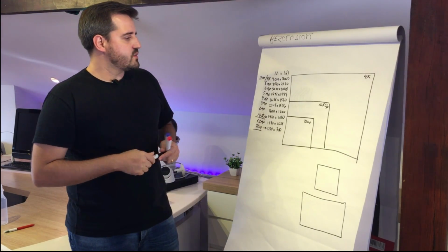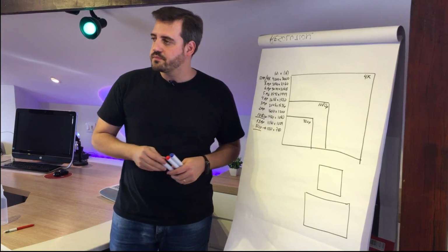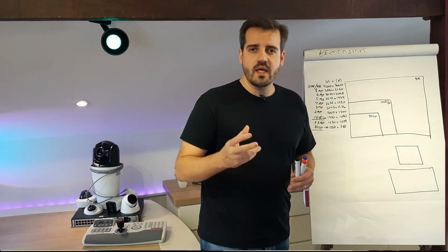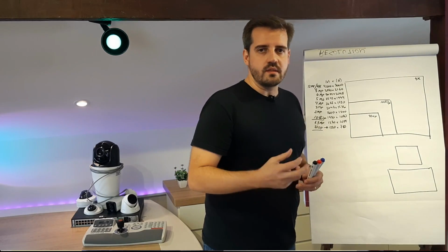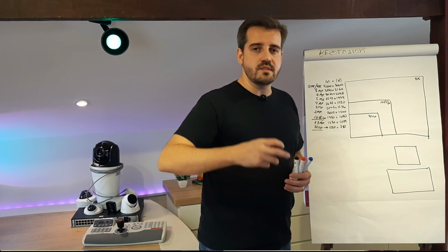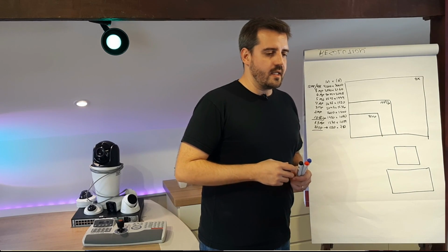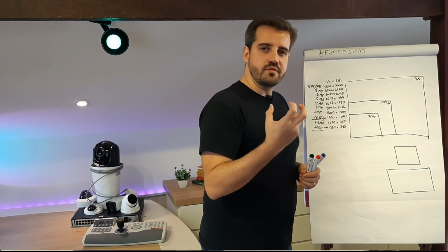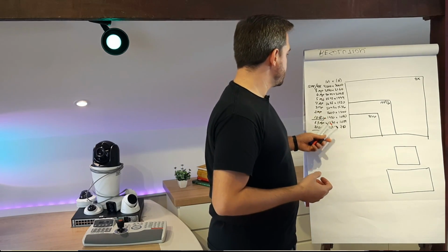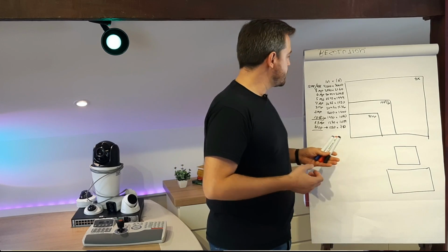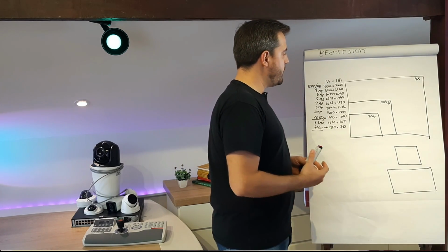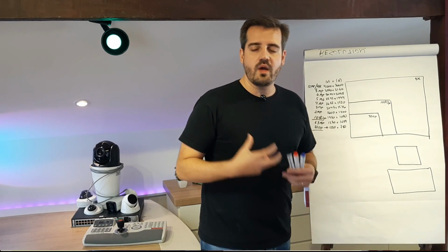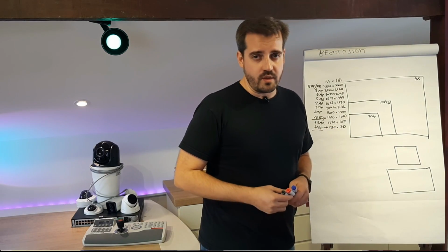So why do we have so many resolutions available? Depending on the project, it's required to get more detail in the image, or if the camera is installed at a specific distance, it will not get enough detail if you have a low resolution, because in the end the resolution shows how many pixels we have in the image. So if we have more pixels, we'll have more details, more information in this image.